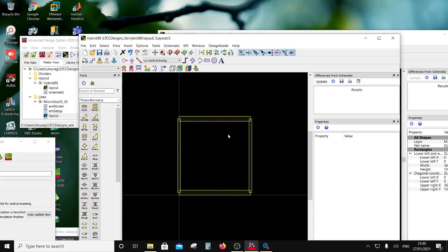You are dealing with frequencies which are not very high, and even if they are high, the dimensions shrink. So these bands really will not do a lot to your design. Rather, if the width of the line is in error, it's going to give you much more error. So this percentage error due to the joins and the pads and everything is very small actually. You do not need to put that in your simulations. And this is from my experience I'm telling, right?